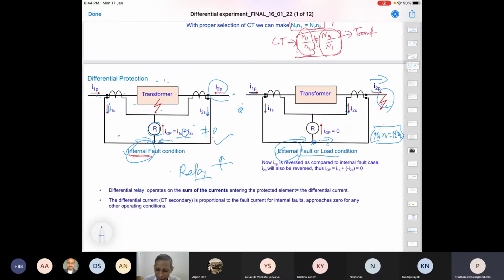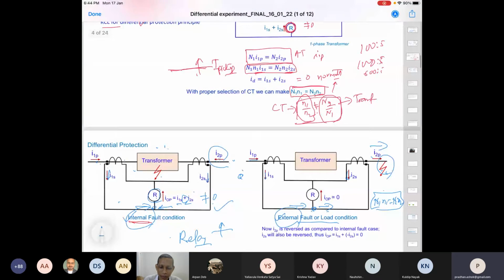What you are saying is that this differential principle has a limitation. Very rightly pointed out. What is the limitation? In the overcurrent relay here, for any fault here, this overcurrent relay can see and make a judgment at a later time. That is the coordination, which you understood in the last class. Now suppose I put a differential principle here for this line. I put this connection like this, and then this is my differential branch current.